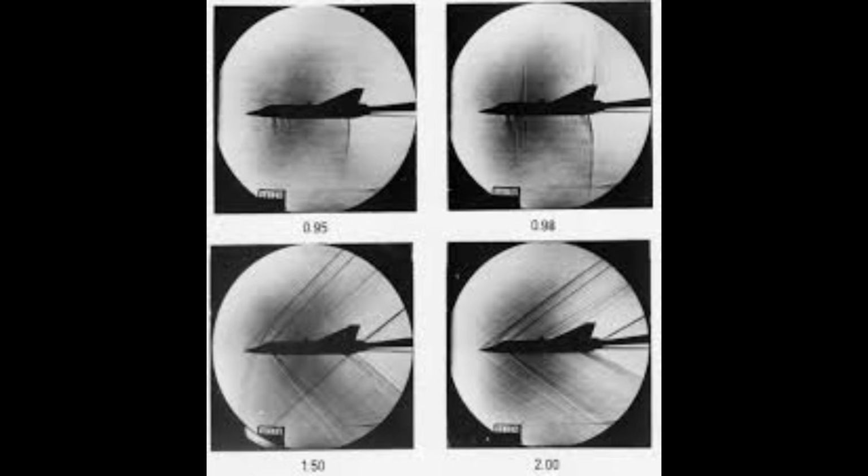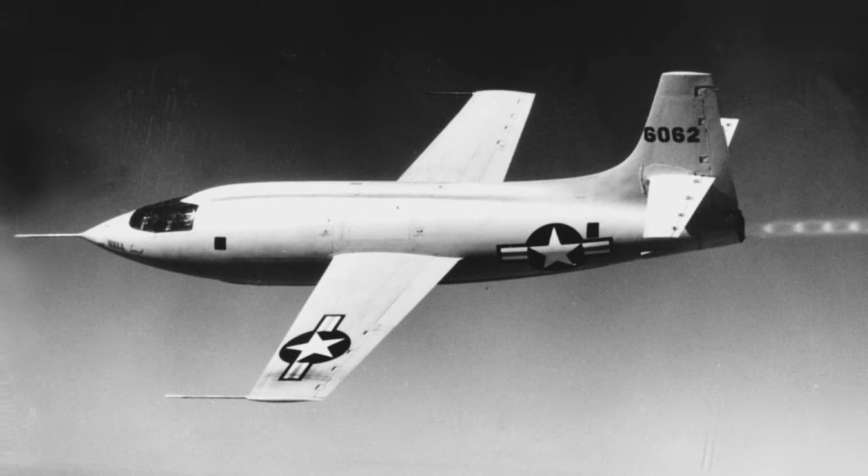Although the aircraft maintained the same forward velocity, the wing saw a lower effective Mach number. This delayed shock formation, reduced drag rise, and preserved lift characteristics at higher speeds. Crucially, this improvement did not require changes in engine power, materials, or structural strength. It was a reframing of the problem.